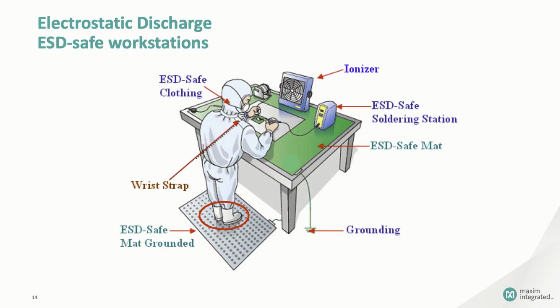In this picture, our hero is wearing ESD safe shoes, but you can get the same effect by wearing heel straps. These attach to the back of your shoes, and a strap goes under your sock to contact your skin. And if the floor is not ESD safe, then you should have an ESD safe mat to stand on. If you have chairs, they should be ESD safe as well, usually with a chain that contacts the floor. You see, you really do have to think ahead when your job is to deliver the best parts in the world with the lowest failure rate.